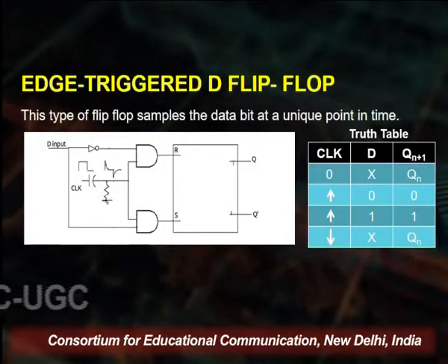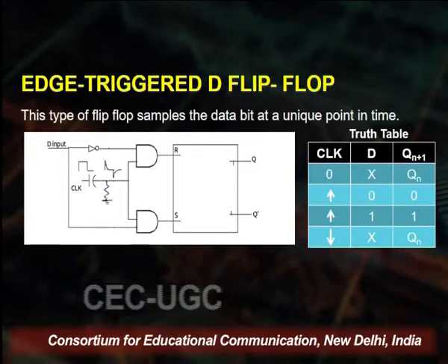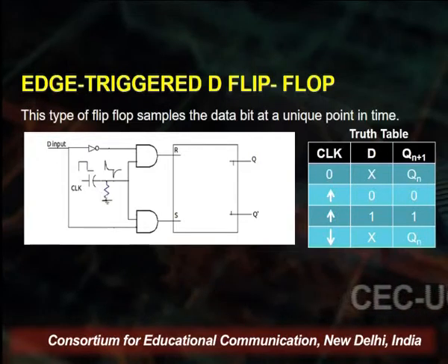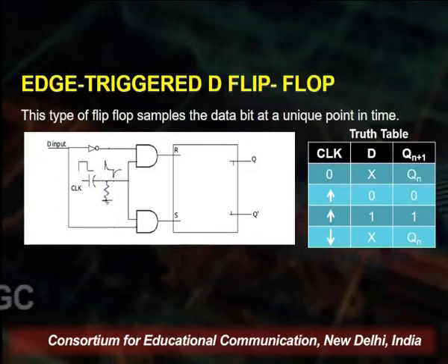If we give a square wave input to a capacitor and take the output across a resistance, then it gives out the output as spikes. These spikes are like edges. So if we had initially microseconds of level triggering, now we can go to nanoseconds of edge triggering, and hence